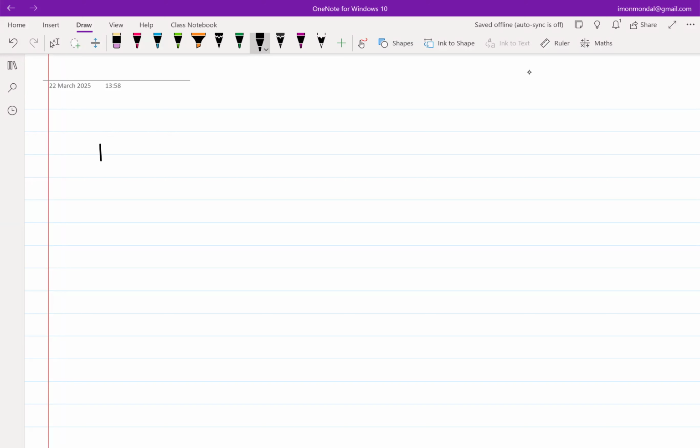Because when we say that I have a load ZL, and I have to invoke a complex conjugate match, it essentially means that the source is also not real. It has a complex part.